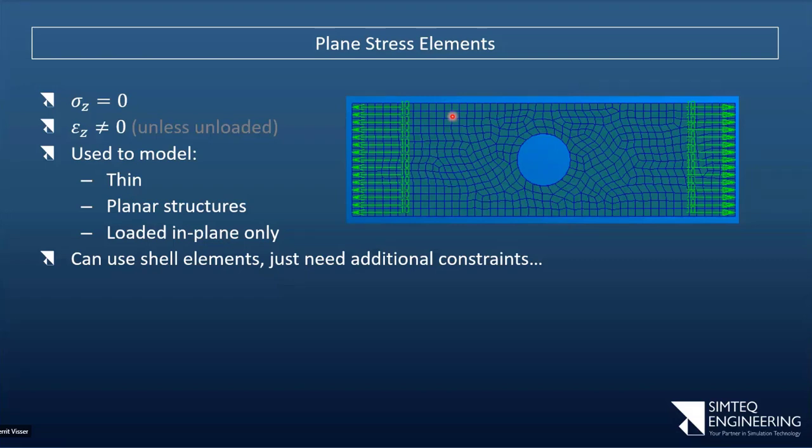So why does that element exist? The reason is if you have a very thin membrane and you apply any kind of either a bending load or an actual compressive load, that is going to buckle, 100% guaranteed. But that doesn't mean that element cannot still transfer shear.